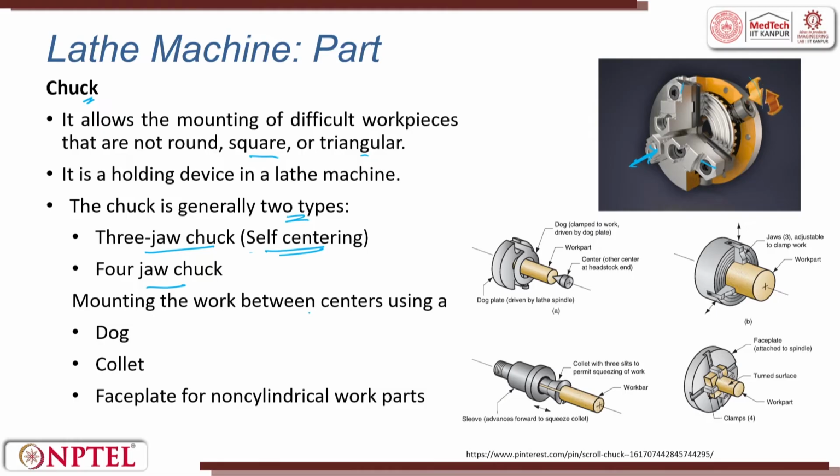Mounting the workpiece between the centers uses a dog. So, this is called a dog, which I was trying to explain. The dog clamps the workpiece. So, this is the dog, right. This is a dog plate. The workpiece is loaded and here you have the dead center which comes in contact. The conical tip is touching the workpiece, right. So, this is the dog plate which is used for mounting the workpiece.